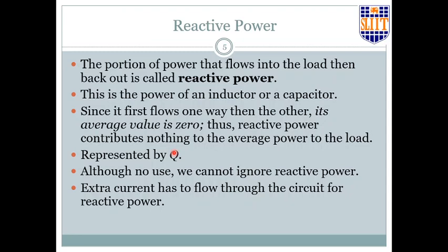Inductors and capacitors have reactive power, and because this portion of power goes into the load and comes out fully, the average of that reactive power is 0, and the reactive power is represented by the capital letter Q. It goes into the load at some time and comes out of the load at another time.